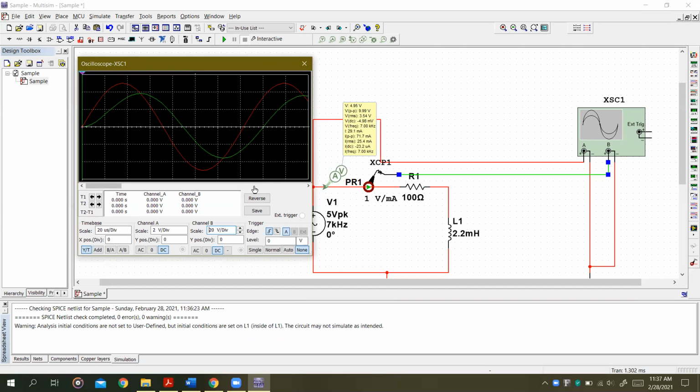Yeah. You have to scroll it right to the start. Okay. So do you see both waveforms? Do you see both waveforms? So set your values to 20 microseconds per division, 2 volts per division, and 20 volts per division. So you should get something like this ideally.